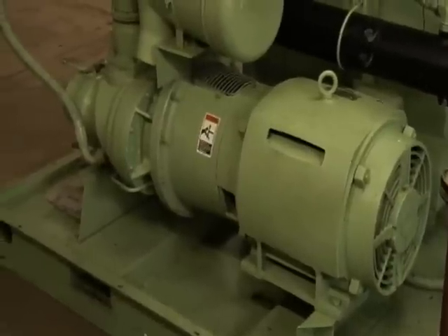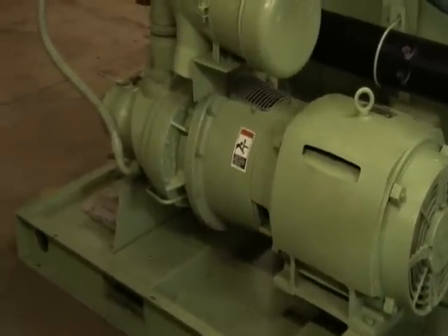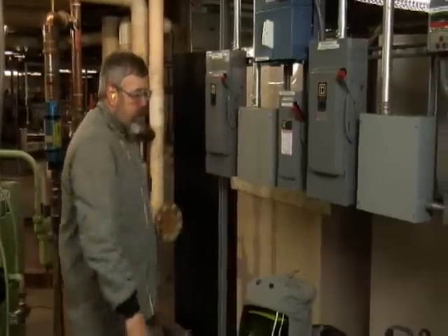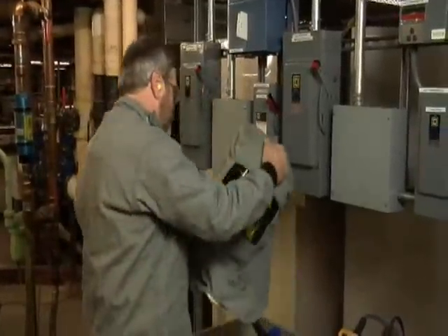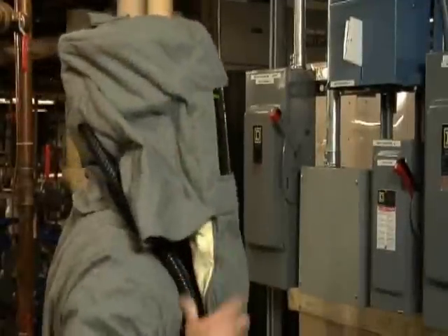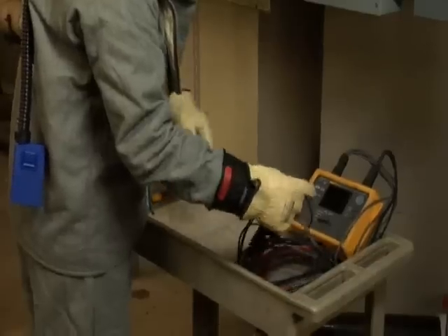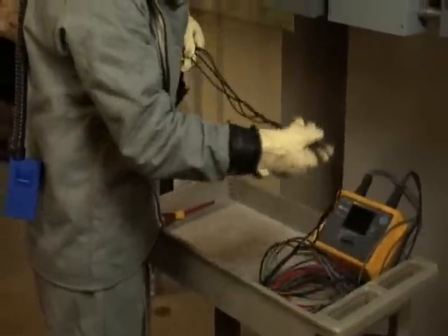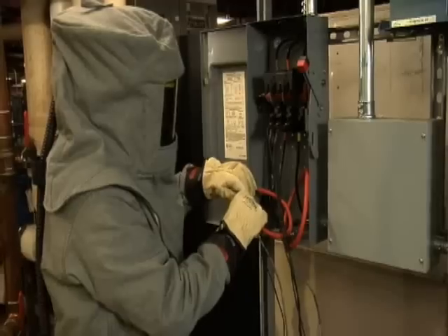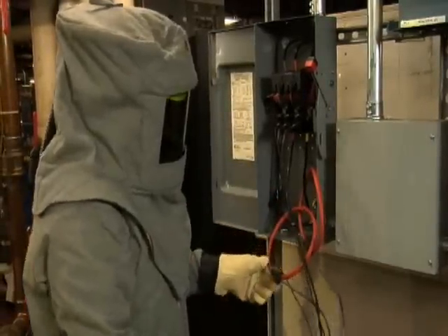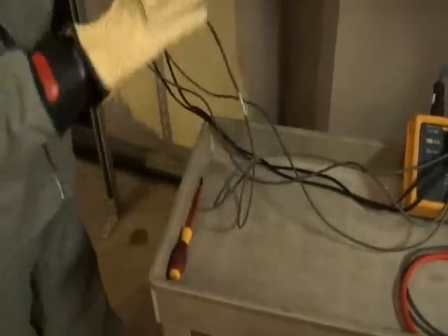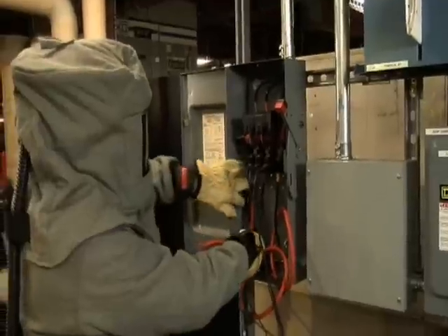This compressor is a good example of a load that's big enough to cause problems with your electrical bill. Again, make sure you are wearing the proper PPE for the job. Always stand to the side as you open and close your doors. Connect your color-coded voltage leads to the correlating connections. Connect the flex current clamps to the matching connections, making sure that all connections are correctly made.